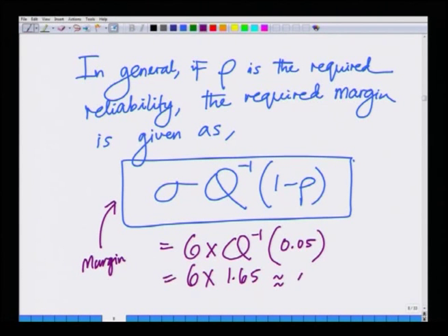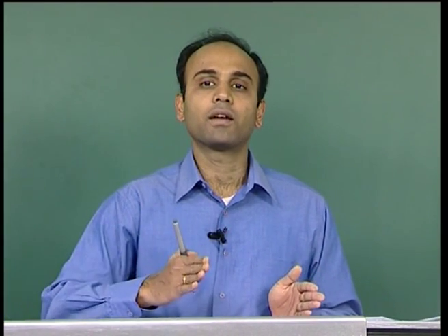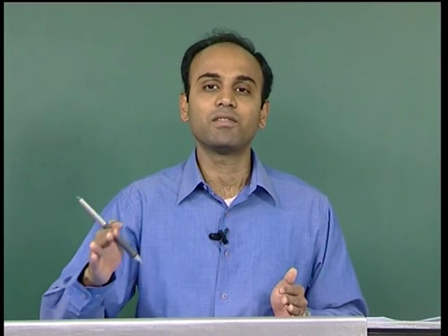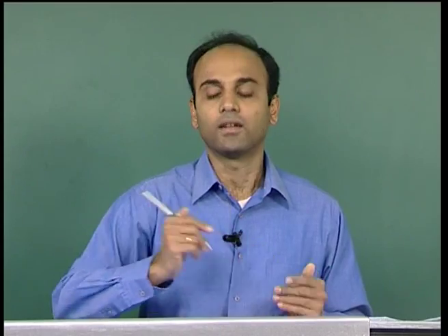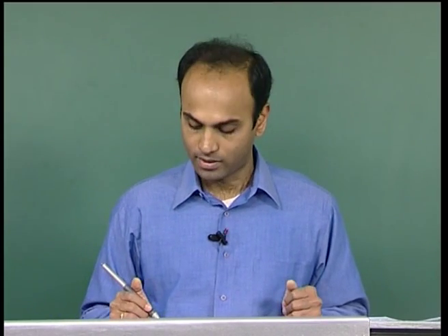approximately 10 dB. So, you can think of it two ways. You can either think of it as path loss greater than a certain threshold, or path loss lower than that threshold with 1 minus that probability, which is essentially nothing but the reliability. So, there are two ways to think about it. One is outage, which is the path loss is greater than threshold. The other is reliability, which means path loss is lesser than that threshold, and the sum of both these probabilities is 1 essentially. Okay.